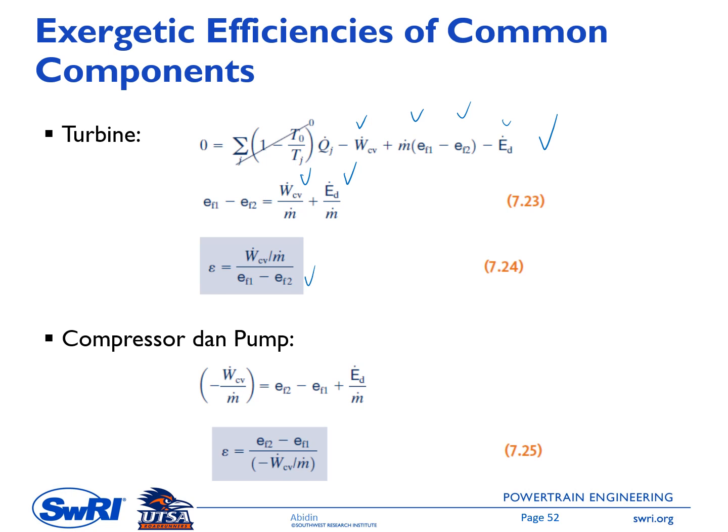Okay. The next one is the compressor or pump. For the compressor or the pump, we need to put energy in, and what we gain is the increase of the exergy at the exit of the compressor or pump. So if we apply the exergy rate balance to this open system, then we have this equation, after we simplified it from this equation. We don't have a heat transfer, so we assume that the process is adiabatic and steady state.